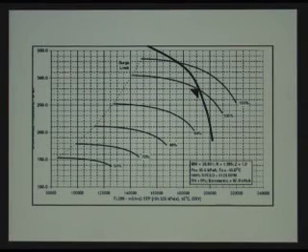On the other side, what if you have an extremely steep performance curve? Certainly you have very good controllability again with your control valve. But the other consideration is we were expecting the maximum pressure to be based upon this flow rate at that speed. All the downstream equipment, all the PSV sizing, was based upon that pressure. Now we find out that the machine is capable of much more, which may mean that all the PSVs need to be changed. The design pressure of the vessels may be inadequate.